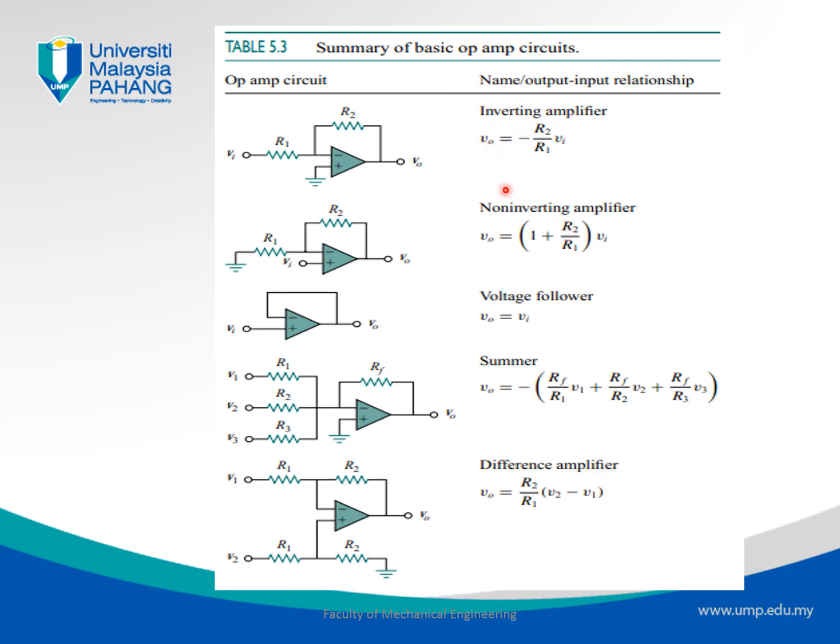So by now we have demonstrated how we go through the calculation by applying the properties of an ideal operational amplifier. The main thing you have to remember is that the input impedance equals infinity, then we can do the calculations that go after that, right? The same thing could be done for others. For those that we have demonstrated, for example inverting amplifiers, non-inverting amplifiers, and summing amplifiers, we can directly use the results that have been demonstrated.